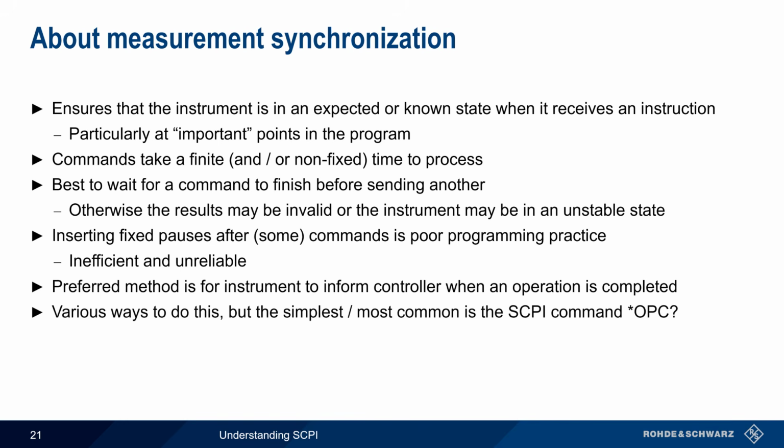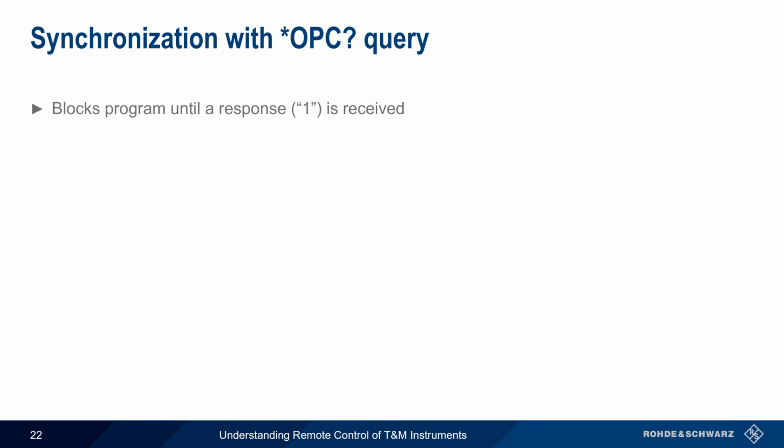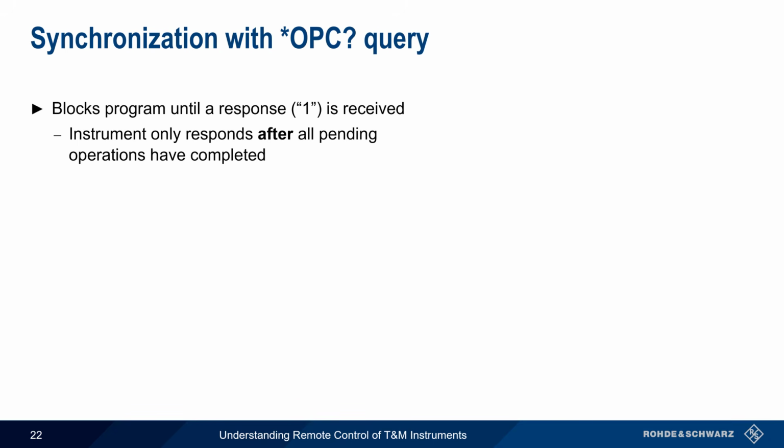There are several ways of doing this in SCPI, but the simplest and most common is the SCPI command OPC, or Operation Complete. The OPC, or OPC query, blocks the program until a response is received from the instrument. The instrument will only respond after all pending operations have completed. The OPC command is often appended to another command, but can also be sent separately.